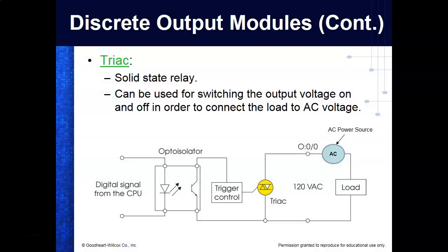Optical latch, we're not going to look at that. Triac. A triac is an AC switch. We call them solid state relays. So what a triac does, it allows us to control AC electronically. So we come up to the output, and what we do is we trigger the triac, and then it'll act like a closed switch, and it'll allow us to run AC loads. Now look,